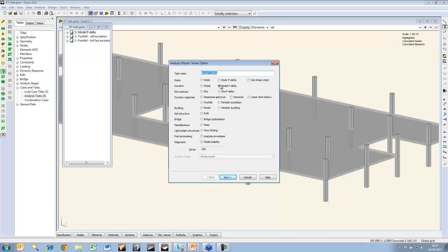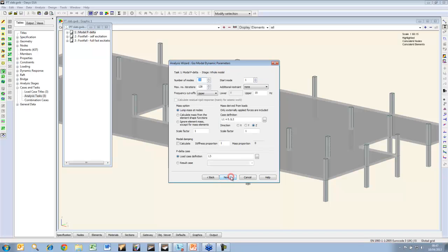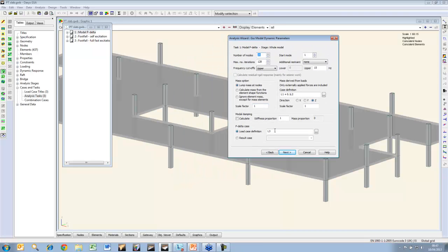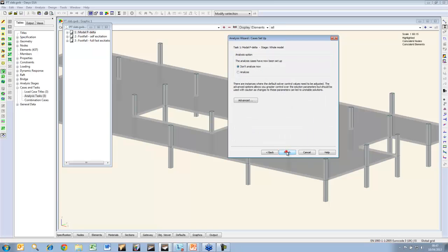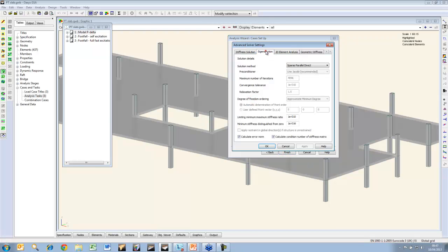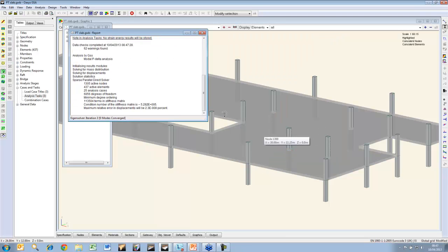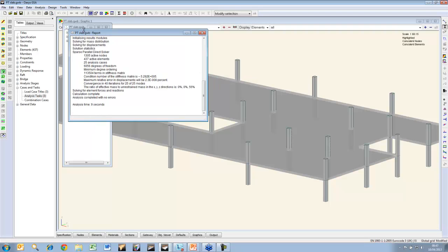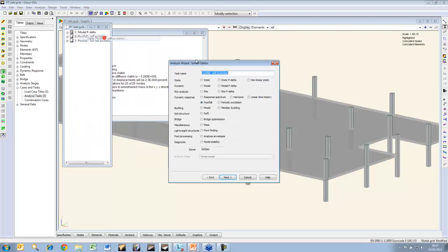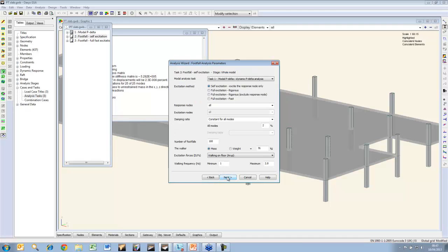If you put the compression on the slab, it will tend to lower the stiffness a bit. I found that, and I've got post-tension forces in there, I found it doesn't make too much difference to a PT slab in terms of footfall vibration, but it can be worthwhile to take it into account. Let me just run the analysis on that, and just run the self-excitation.